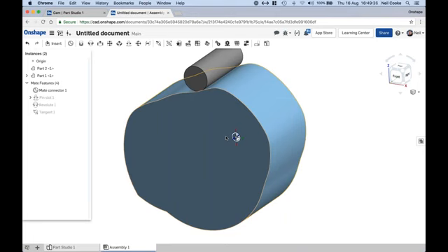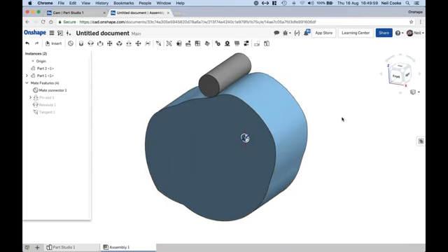And then for more complex things, like cam profiles, it's not something which you'll find in the user interface, but you can add a custom feature written by the community to do that. And the nice thing is that as we've built this custom feature to build this cam, like we've seen, make any changes to the features, the sketch, and everything is going to update for you automatically.